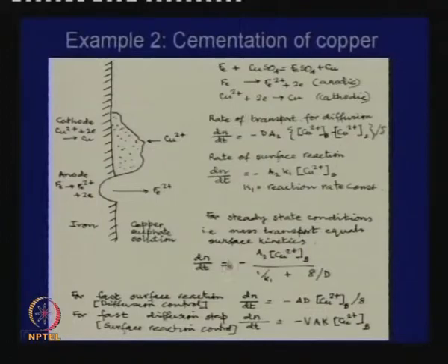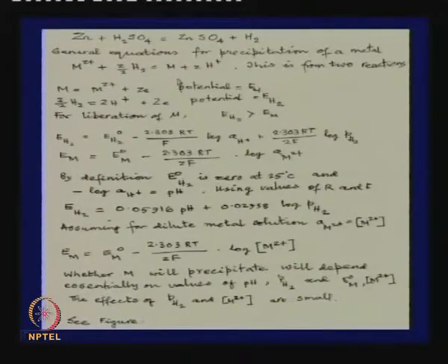We made an analysis to understand what factors will govern the rate of the cementation process. It is not very difficult to understand. Then we have come to a very important area, and we looked at it from a thermodynamic point of view, that zinc, when it reacts with H2SO4, releases hydrogen, because zinc is more electropositive. We can write a general thing that a metal which is more electropositive displaces hydrogen ions.